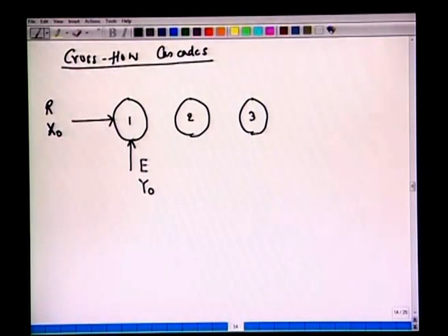Now, if you recall from our previous lectures on continuous contact processes, we said that it is simpler to work with capital X and capital Y, which are on a solute free basis. If we have binary components and only one component diffuses from one stream to another, then it is convenient to work with capital X and capital Y mole fractions as well as molar flow rates on a solute free basis, because we realized earlier that operating lines in such cases become linear. So our mathematical computation becomes simpler. Here also we will work with solute free mole fractions and solute free molar or mass flow rates.